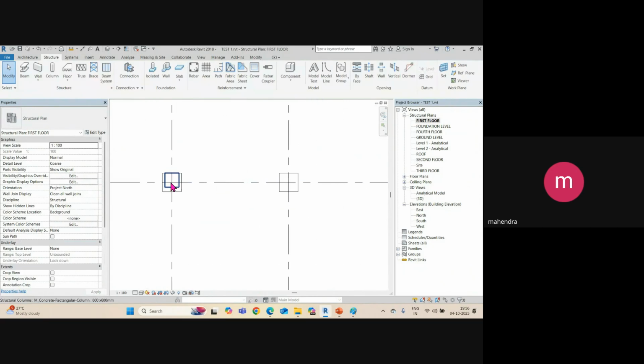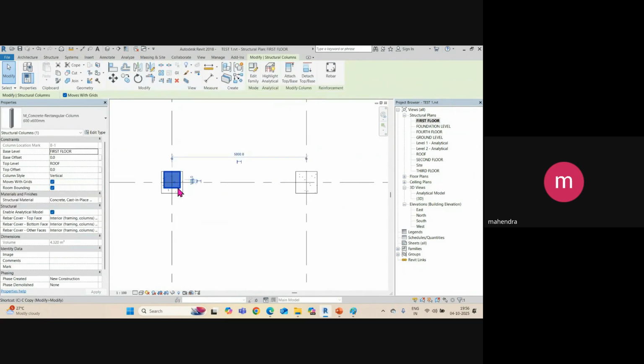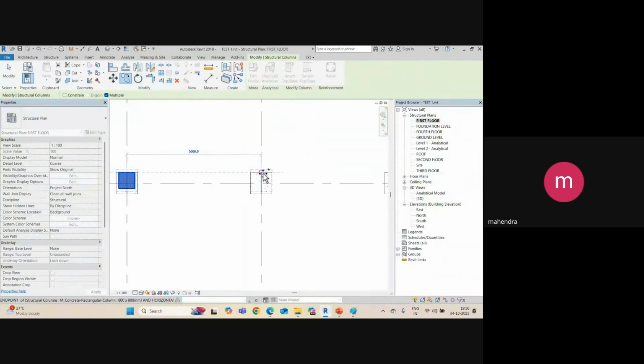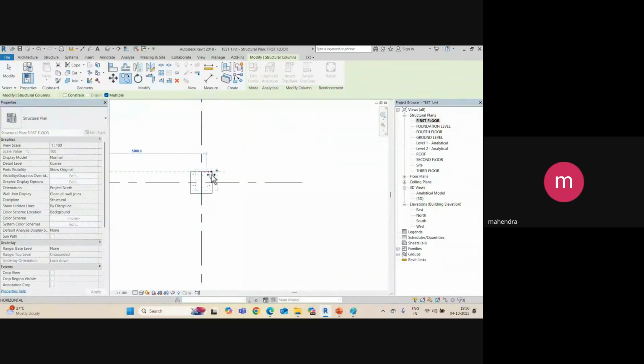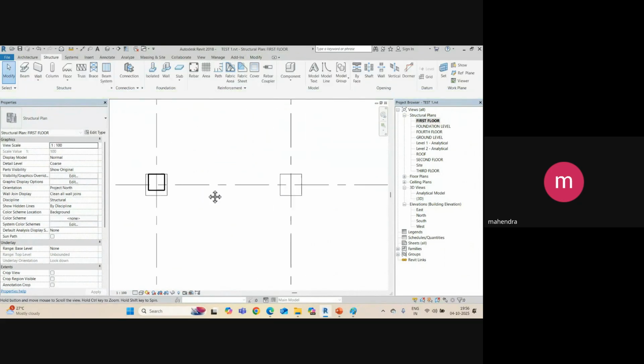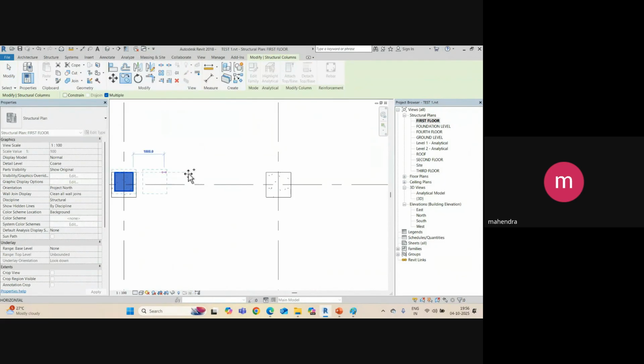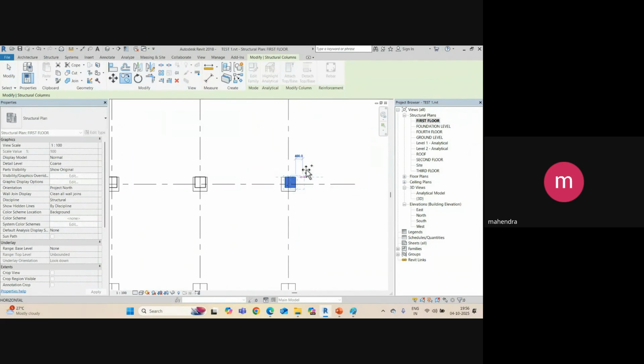this location is the same. So select again, type CO, but I want to paste at multiple locations. So click on this option, Multiple, and then you can add at multiple locations here, and you need to add the corner condition column here. So select, type CO, and you can add here like that.